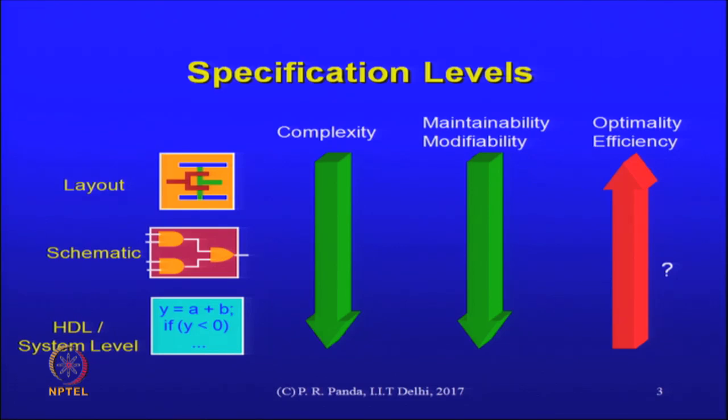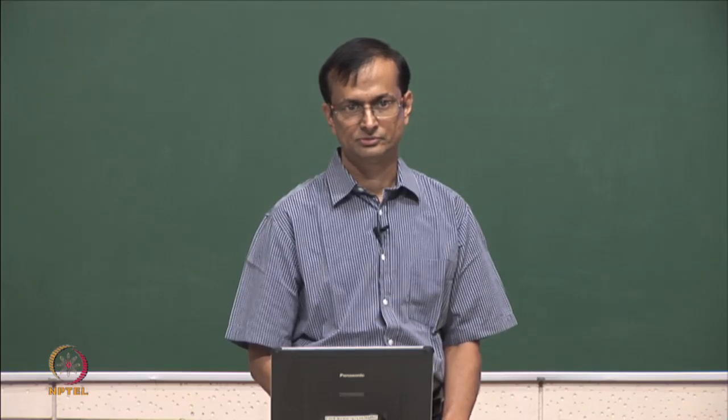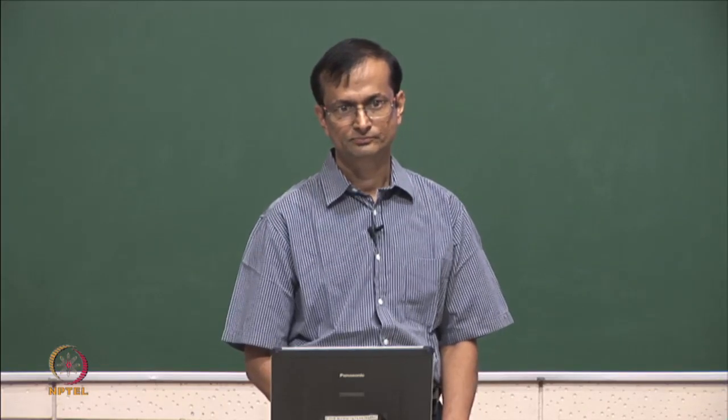Yes, in fact, we already talked about memory being an example where you actually enter the essence of a memory cell through a layout. It is so important that you can afford to spend all that time to design the system at the layout level. If you want to optimize the area beyond the limits of the technology, then you would go custom, like memories. Right. The bit cell is highly optimized. Yes, it does depend on the context.